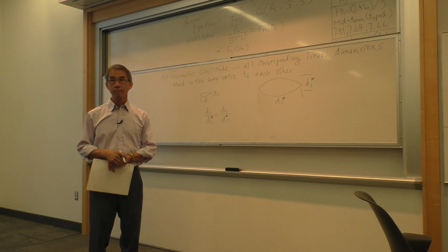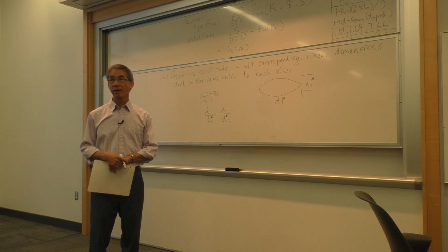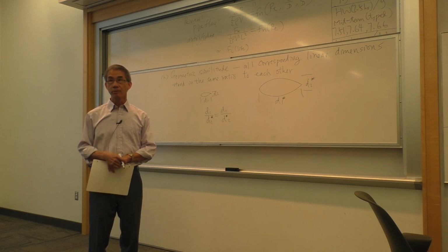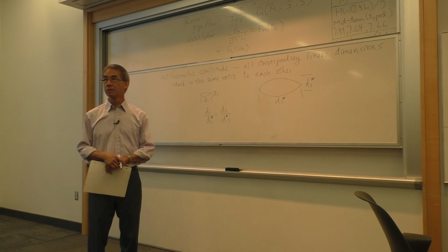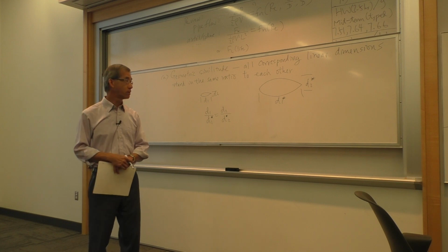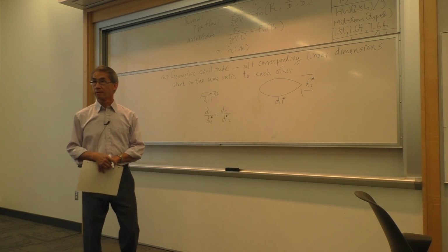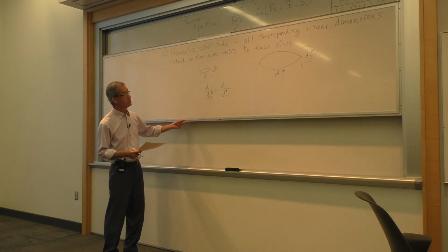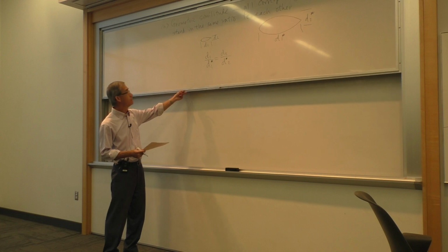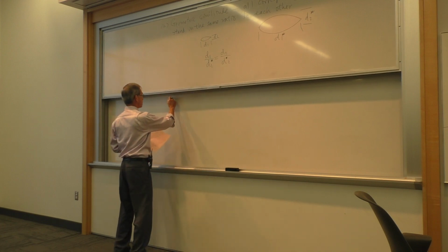They are small, maybe in the actual size micrometers, a fraction of an inch, and when you shrink it down by 100 times, there's just no way you can reproduce that surface roughness. So that alone, obviously, is something you cannot match in the wind tunnel. All right? But you do the best you can, and this is the first and relatively easiest criterion to meet. Second,